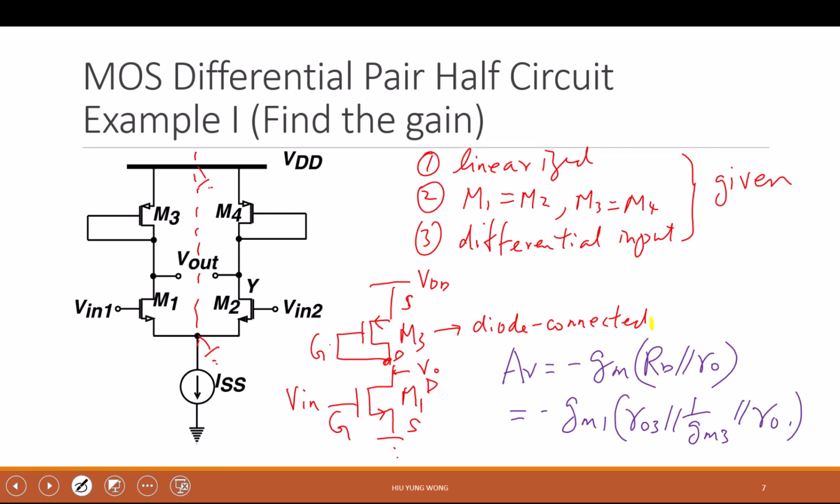All right, excellent. So you do need to know this, right? So very good. This is RD, right? So you do it step by step. We solve this complicated circuit in such short time. But sometimes it's not that we solve it fast. On the other hand, you see this, you can design a circuit from there. Even if you know how to solve it very fast using KCL, KVL, you don't have the insight. I ask you to design a certain differential amplifier. You cannot do it by thinking about KCL, KVL.